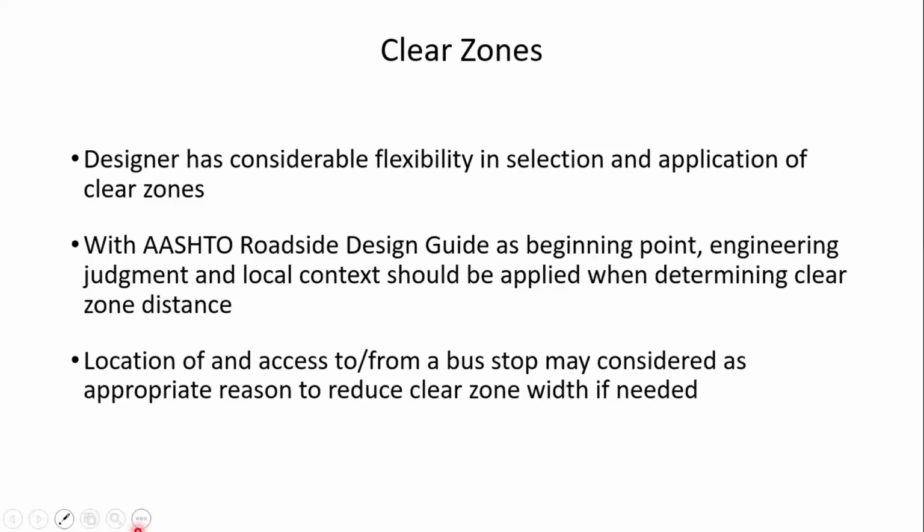In terms of if there's a structure or shelter used at the bus stop, then the clear zone concept may come into play. And here we're talking about the AASHTO Roadside Design Guide. That's kind of a good starting place, I guess, but you probably need to use engineering judgment and consider the local context when you're determining clear zone distance.